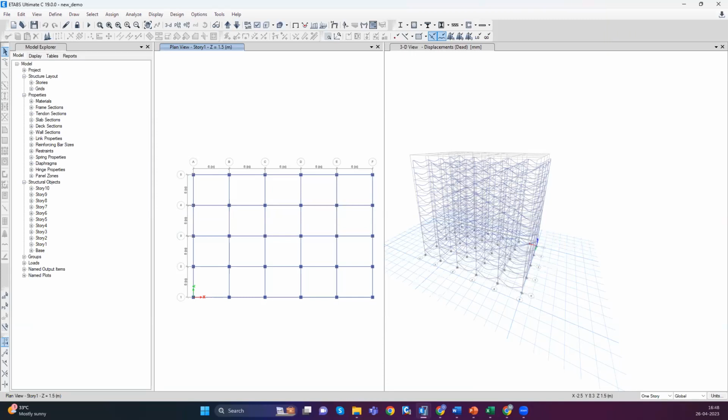Okay. And one of the participants is asking about these levels, right? Immediate occupancy, collapse prevention, the performance levels which are mentioned in the different guidelines. Whether they need to be changed as per the requirement, do these values really vary as per the structure height in particular? I would say it depends upon the requirement on the site, what the code specifies, and also what type of material we are choosing. Because the stress-strain curve will follow the material behavior you choose, so you need to ensure when the linearity is moving towards the nonlinear range.